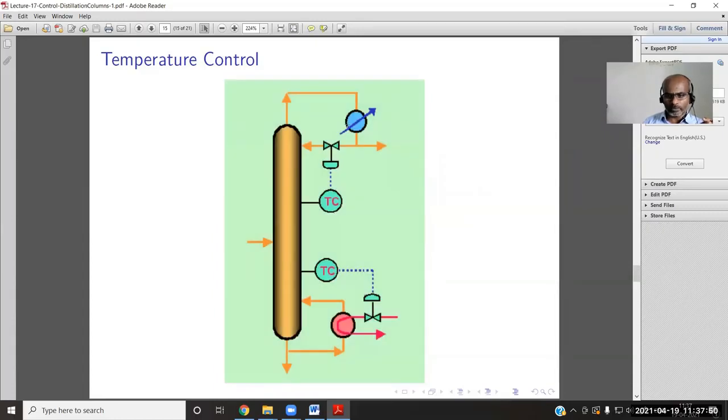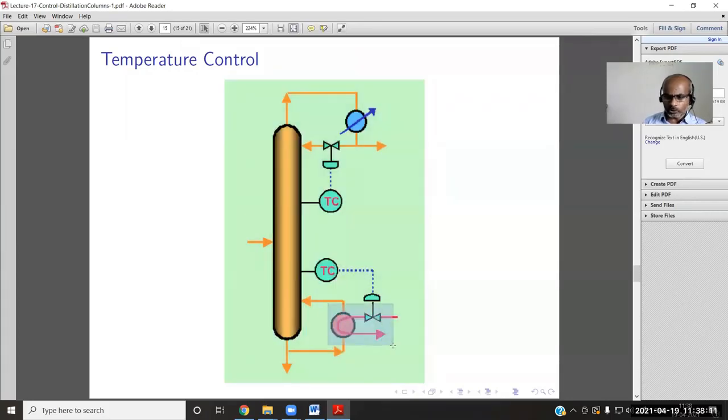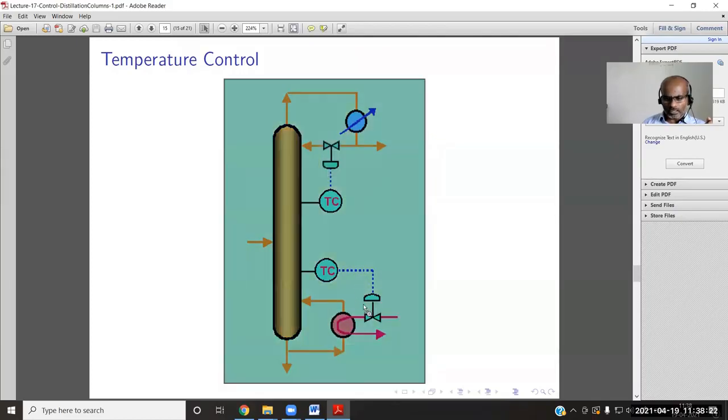Adjusting the reflux rate means that if you increase or decrease the reflux, it will affect the total column, and it will also regulate the associated coolant flow. You can adjust this reflux also. Likewise, the temperature control at the bottom is by adjusting the heating to the reboiler. Otherwise, the most common control is simply adjusting the reflux rate and the reboiler rate.